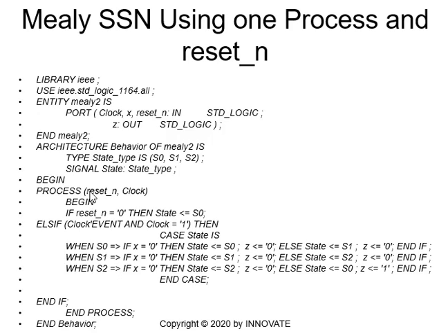So in this code, we only added reset_n to the code, and this is an asynchronous reset to the whole machine, and it is active low asynchronous, and this is why it has to take place before the statement of the clock. Okay.